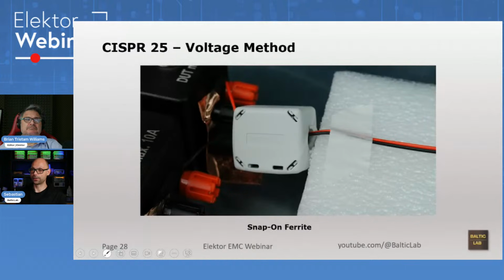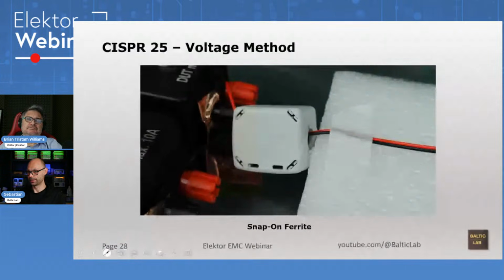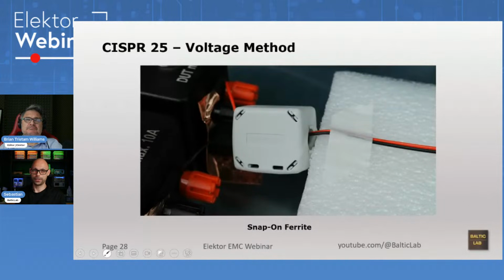So the first thing that I always read in my comments, really no exception, is either going to be capacitors or ferrites. Now, there is a funny graphic that correlates the amount of ferrites used to the skills of the design engineer. The more ferrites you see, the less skilled the design engineer is. Ferrites are oftentimes a last-ditch effort to gain a few dB of freedom when some product has failed. Never at any point should ferrites be your primary EMC solution.